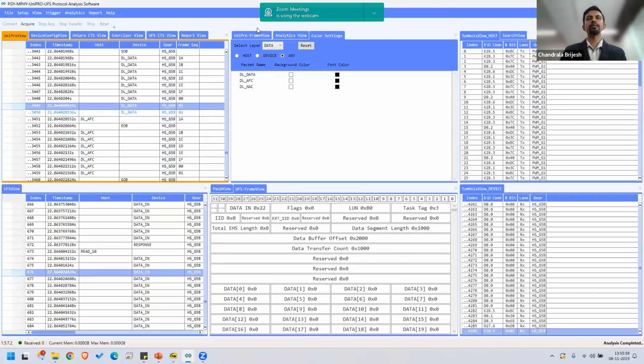Yeah, Pranav, next question. The next question is, if buying the analyzer or exerciser, what are the standard accessories and probing solutions provided? If you're buying only the analyzer, we have an option of selecting either soldered-on probe tips or mini SMP probe tips. Optionally, a B2B interposer, which is board-to-board, and a power divider interposer for pre-silicon are available. And if you have some unique requirement, we can also provide a custom probing solution.